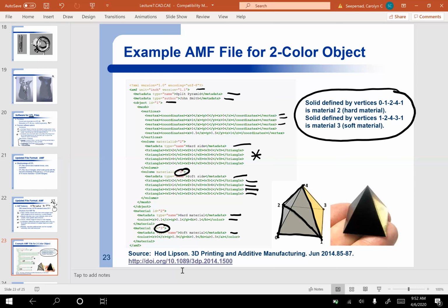All right. Okay, so one of the things I encourage you to do, just to get used to this, is open up a computational geometry CAD software. Many of you have access to SolidWorks. If not, you can also use any other geometry software, the equivalent of Google SketchUp, anything else you'd like to use to generate some geometry, and then try generating some STL files, right? And look and see what those triangles look like, and if you can figure out how those triangles correspond back to the part that you built.